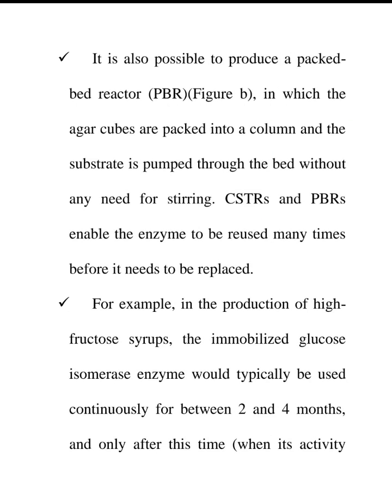It is also possible to produce a packed bed reactor, PBR, shown in figure B, in which the agar cubes are packed into a column and the substrate is pumped through the bed without any need for stirring. CSTRs and PBRs enable the enzymes to be reused many times before they need to be replaced.